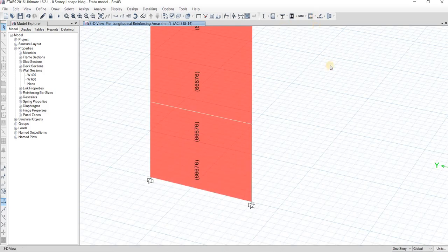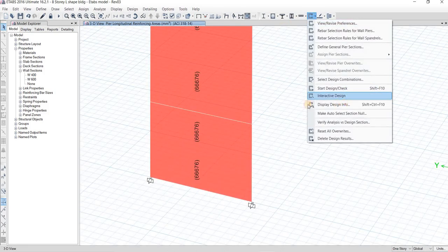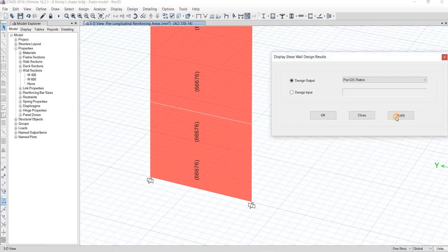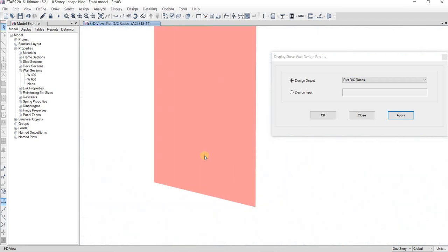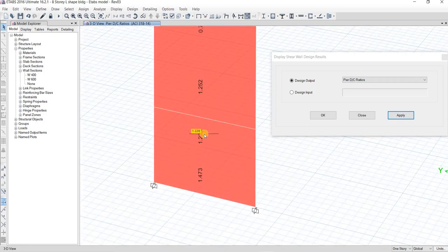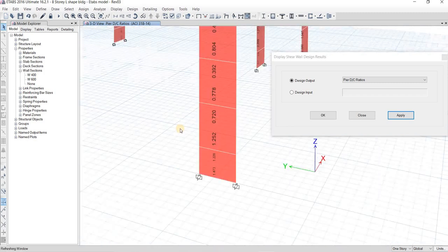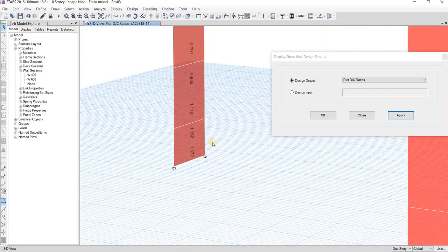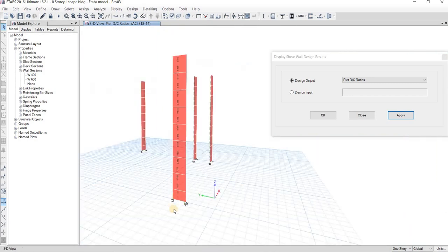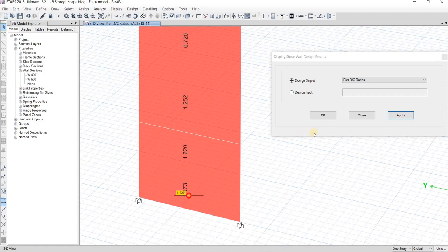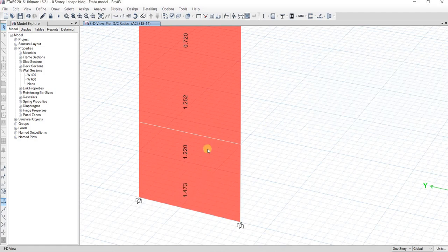Then you will go to the DCR building ratio. This is 1.47. So you will notice, or you will understand, that when we jack up the rebar, the demand over capacity is decreasing because we increase the capacity. So by iteration, you can do it again to make it less than 1.